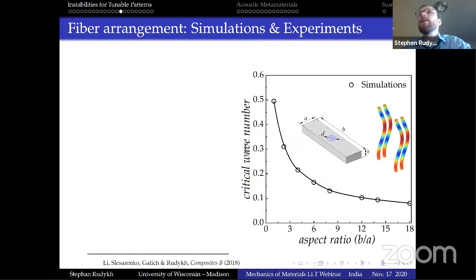of 5. And it's interesting that there are certain configurations for which fibers will buckle into a different direction than one would expect. At least I expected, at certain points, the fibers always to buckle in the soft direction. However, for certain configurations, they prefer to do a very strange mode of buckling, where they cooperatively buckle in this direction, which is counterintuitive.